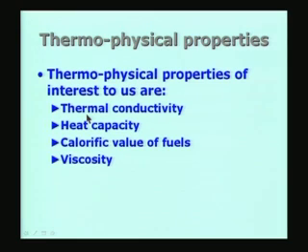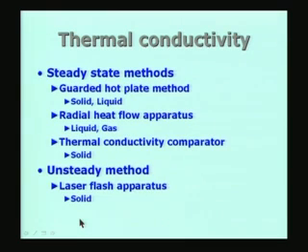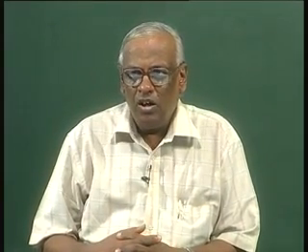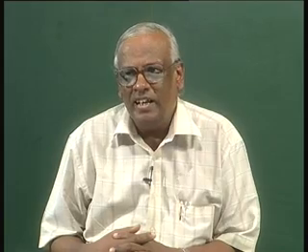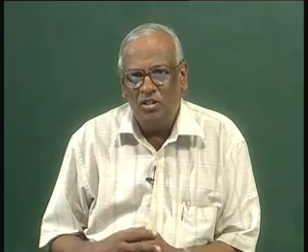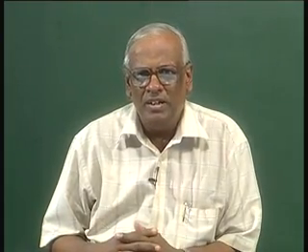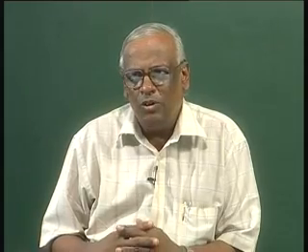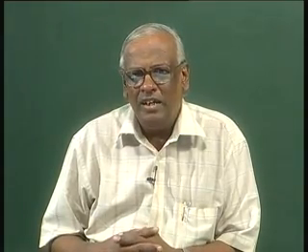The first thing I am going to look at is the measurement of thermal conductivity, and of course we will go on to the other topics as we go along. Thermal conductivity, as you very well know, is a fundamental quantity of interest whenever we talk about heat transfer in any material, whether it is liquid, gas or solid. And when you talk about conduction, only conduction heat transfer taking place, it is only in the case of a solid, assuming that of course the solid is stationary and there is no possibility of much movement in the macroscopic sense. So solid is the only case where thermal conduction can be actually studied in great detail.